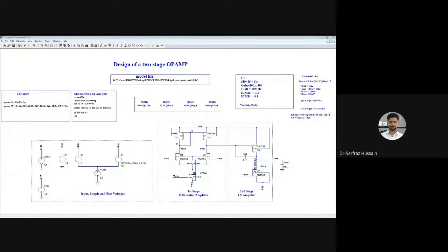So that is why I'm keeping this common mode voltage as 1.2 over here, so that I will get a good output. Now I have kept the common mode voltage as 1.2, and now I will check for different types of simulations. So what are the simulations that we will do for the op-amp circuit? The simulations can be a transient analysis, AC analysis, DC analysis, noise analysis, transfer function, or just the operating points. So let us first start with this one.